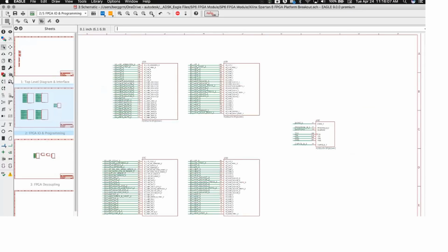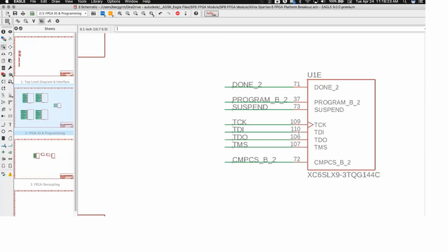So as we started to play around with that, one of the things that I tend to do, and this is something which I understand is not terribly common amongst the Eagle user base, but is something that we're hoping to push moving forward, is I tend to group signals together into buses. So, if I take a look here over at the JTAG bus, I would typically associate these 4 signals into a bus, and then I would try to move that bus sheet to sheet, document to document, whatnot, as a group. And that just allows me to work at a higher level of abstraction.